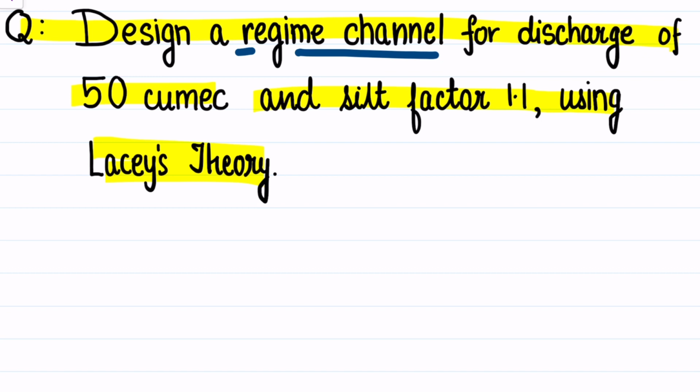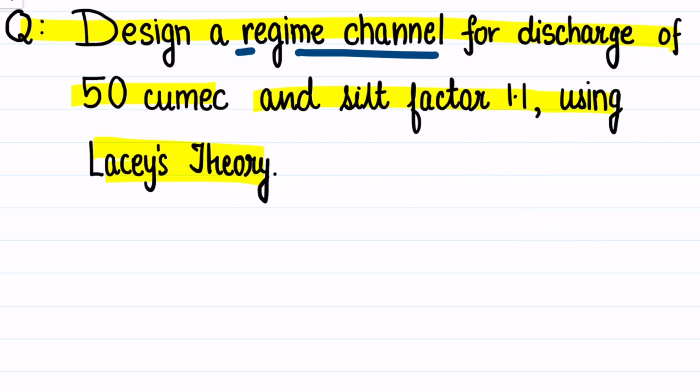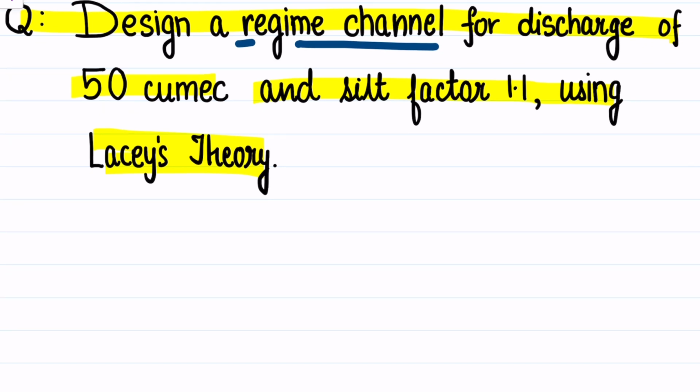Unlike Kennedy's, where we had to assume a certain trial depth and then find out the critical velocity, then follow certain steps, then find out the actual velocity and see if the critical velocity is equal to the actual velocity. If not, then again we have to assume a new trial depth and so on. So unlike that, Lacey's design of regime channel is a very straightforward methodology. So let's solve this question using Lacey's design of regime channel.